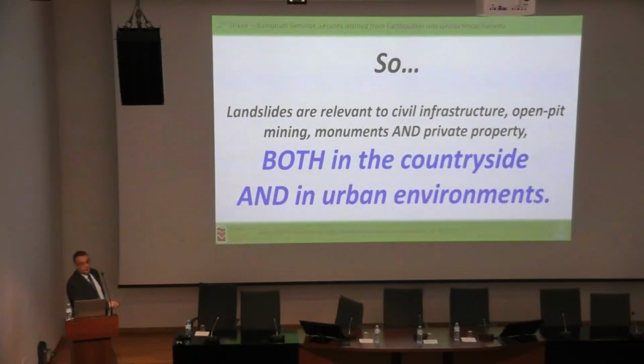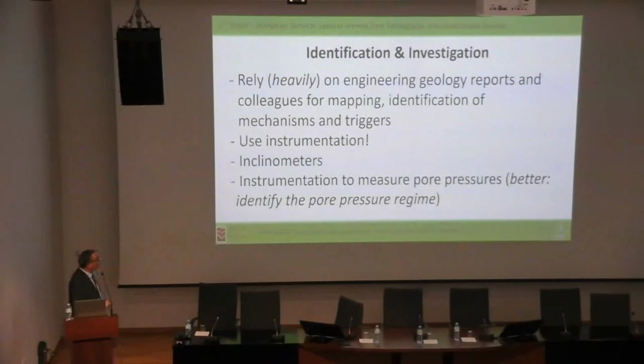And what I'm about to present in the rest of my presentation is a few basic things about the identification and investigation, not much on that, but I will focus more on the selection and a possible use of some logical diagrams for the selection of stabilization measures. So for identification and investigation, we are going to rely heavily on engineering geology and our engineering geologist colleagues with their reports and mapping about what is happening and where, the identification of mechanisms and triggers, use instrumentation, a lot of instrumentation, inclinometers and instrumentation to measure pore pressures.